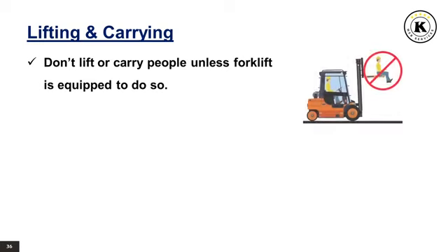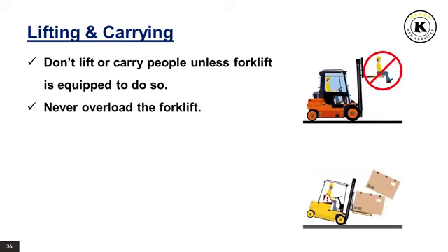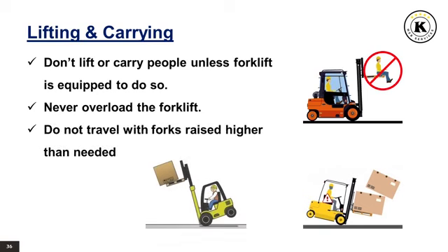Lifting and carrying. Don't lift or carry people unless the forklift is equipped to do so. Never overload the forklift. Do not travel with forks raised higher than needed.